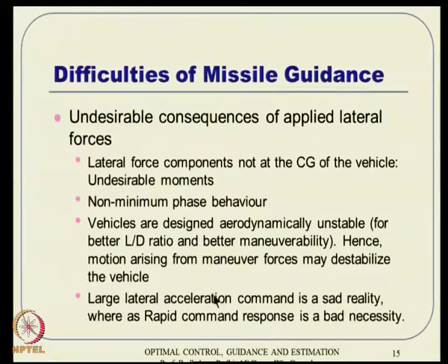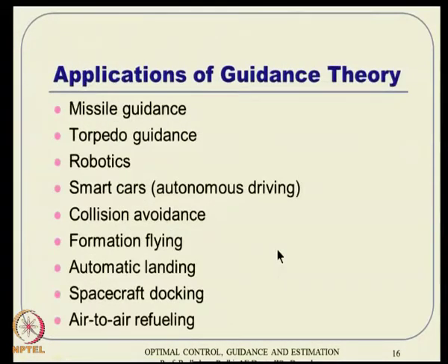For example, some air to air missiles talk about 20-30 G of lateral acceleration, which is quite large. So, that is a sad reality, and rapid command response is a bad necessity also. That is where you have to be extremely careful that some effects do not come which will destabilize the vehicle. So, these are typically the difficulties of missile guidance.